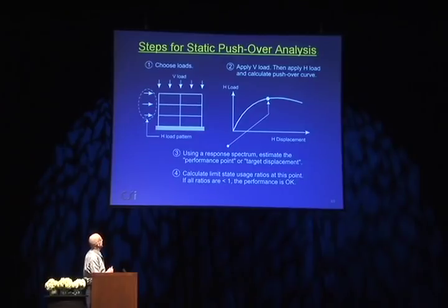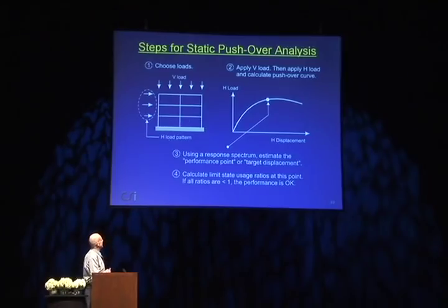In this case, this looks almost like a uniform load pattern. You might be linear, or you might base the load pattern on the mode shape. Or you typically would have several load patterns and run a number of different pushover analyses, one for each load pattern. But you don't worry about the magnitude of this at this stage, just the distribution.